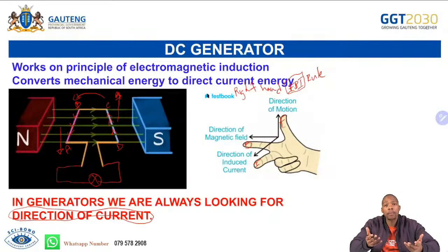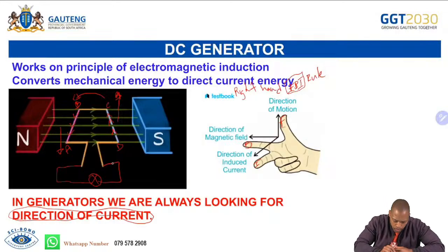What could be the problem again here? We have a problem of the design. We have designed a very, very poor generator, if we put it like this. How come? If we start rotating this generator, we're going to have problems with these wires as they twist and turn, and they are tangling with each other. Therefore, we cannot put the load directly into the coil.